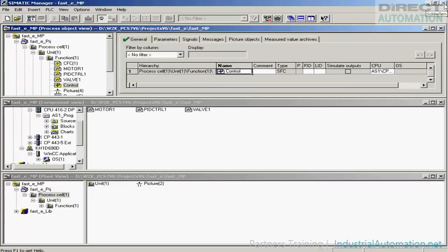The sequence of operations is now defined, and the SFC editor is closed. The sequence of operations called Control switches the motor 1 on as soon as the process value PV-in goes above 50. After 10 seconds, the motor is switched off again.